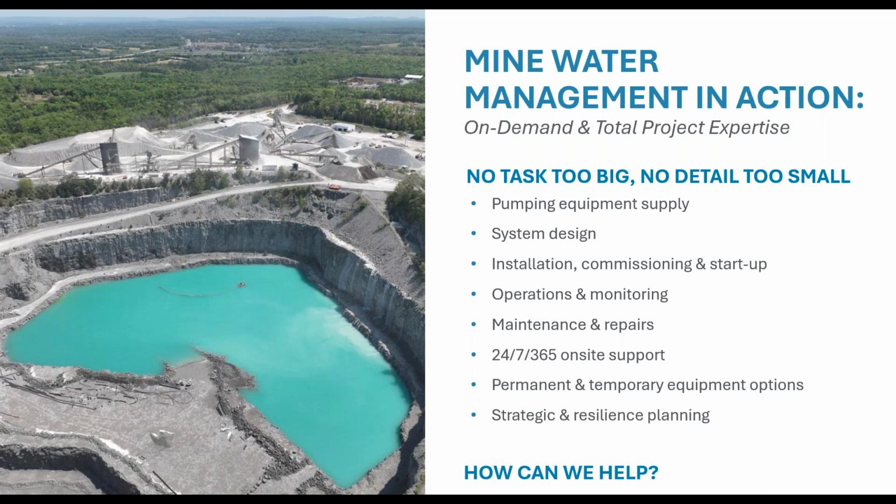But a quick fix could be to suspend the pump so that it's not sitting down in the muck at the bottom of the sump. This would help improve the longevity of the pumps in that application. If it's not clogging, it could be an indication that they're operating basically too far out on their performance curve. Too much flow, not enough head.